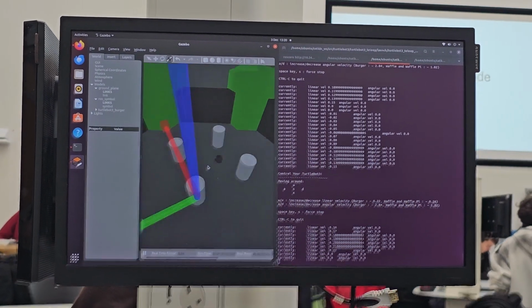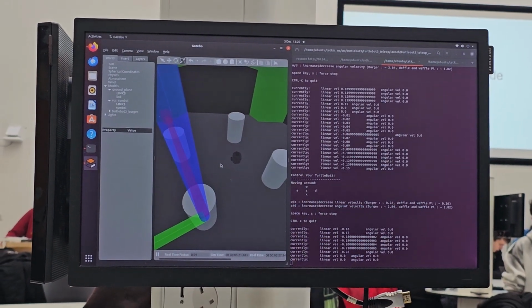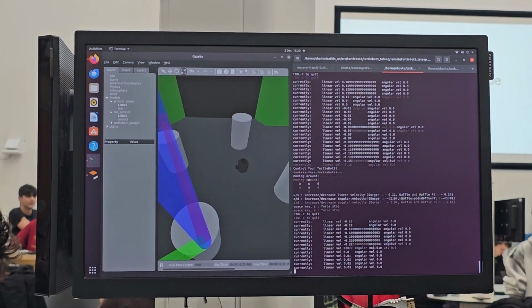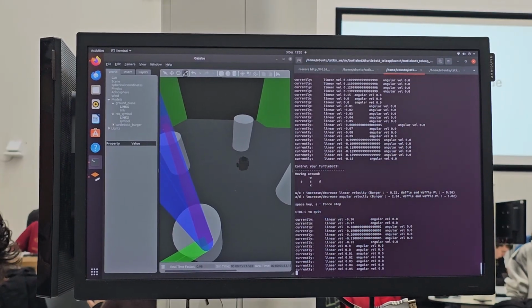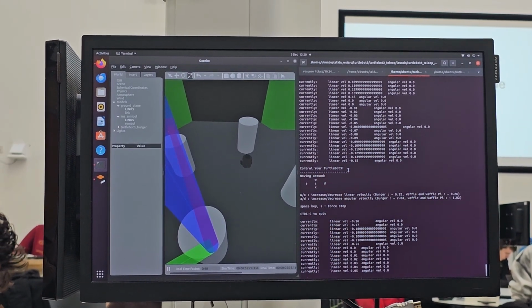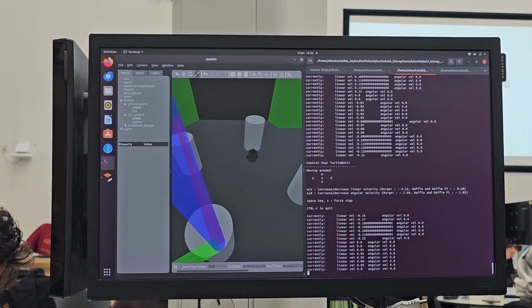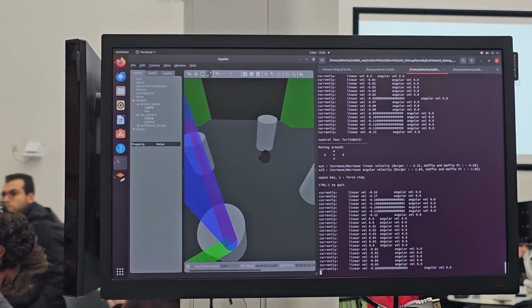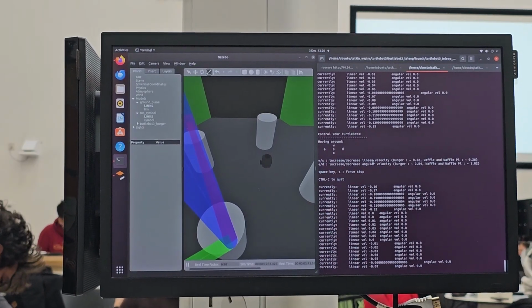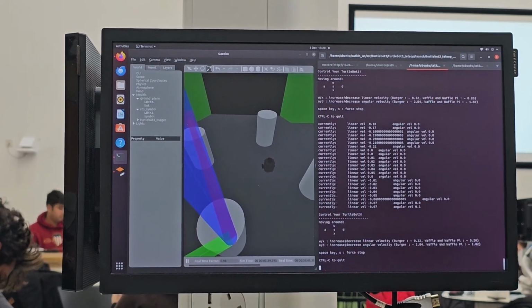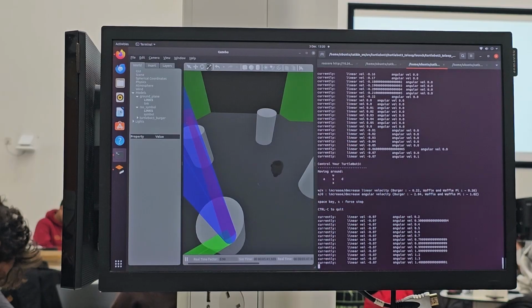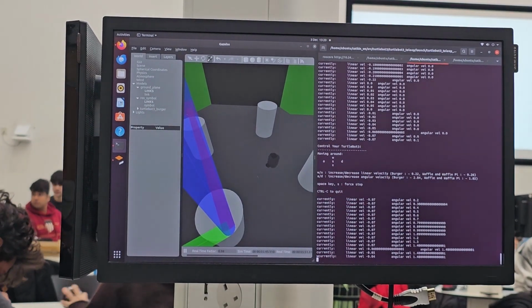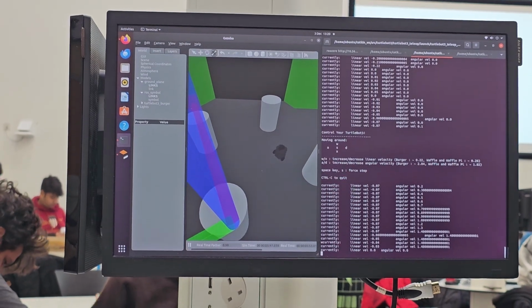With hardware and connection verified, we transitioned to the Gazebo simulator. We launched the virtual Turtlebot 3 model to test our control logic in a safe environment. Using keyboard teleoperation, we drove the robot within the simulation, validating the kinematics and ensuring the software environment was correctly configured for further tasks.